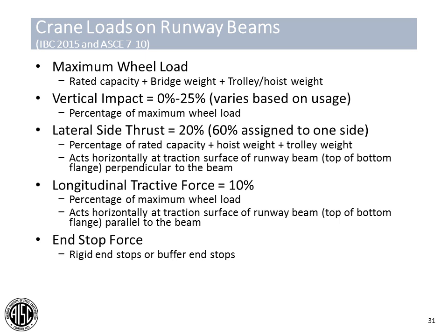Generally what is done is you take each independent wheel load and you would apply a tractive force. There is friction between every wheel and the top running surface of that bottom flange. So you would take a percentage of the maximum wheel load of one particular wheel and apply it at multiple locations.